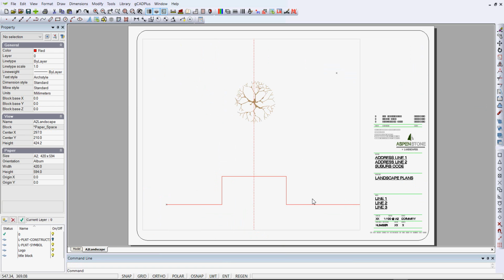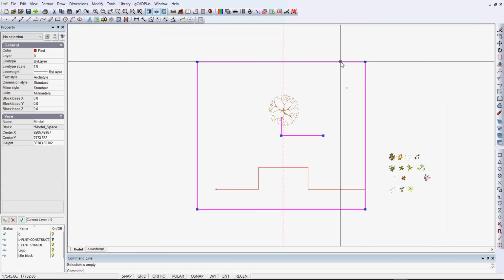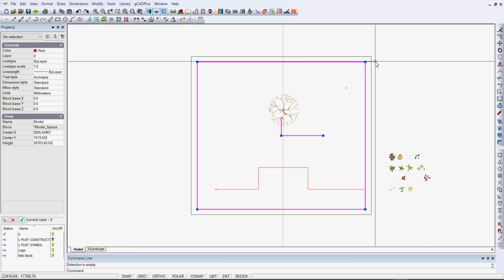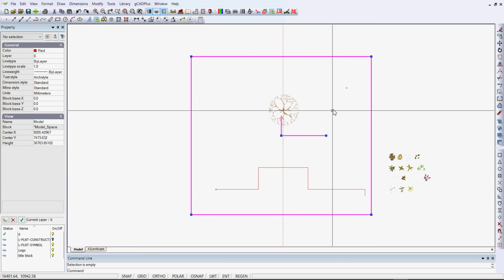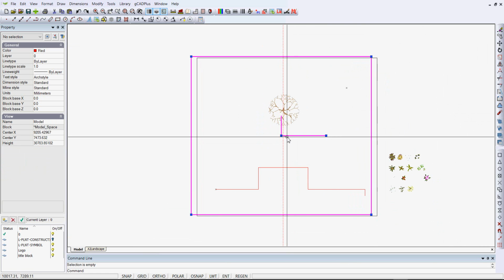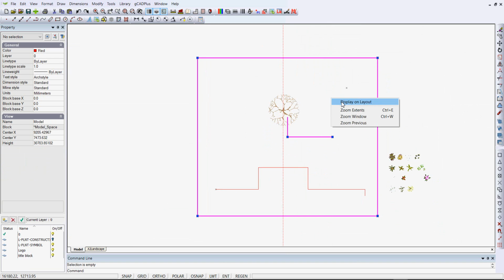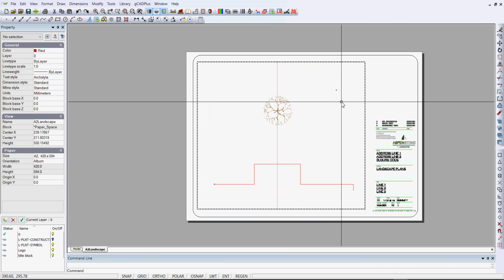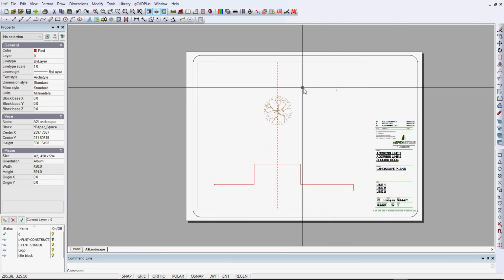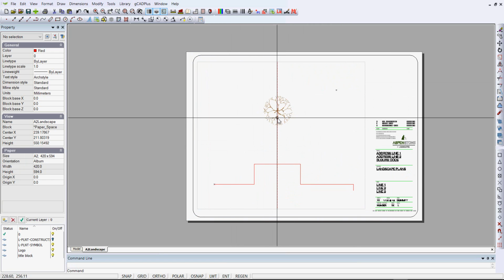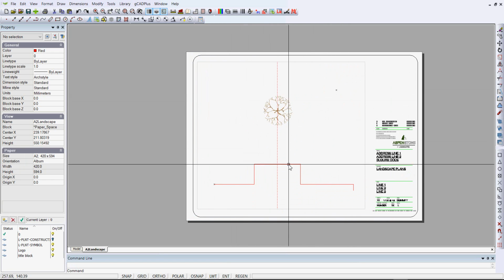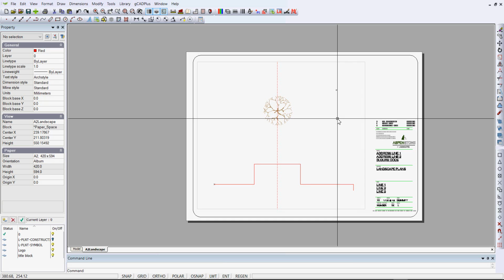So I could notice how the line there doesn't quite reach. So I could double click there and just expand what's going to be shown on the page. I can move that across a little and right click and display, and then double click to get rid of it. And you see that whatever we draw rather magically appears inside this floating view. It's called a floating viewport.